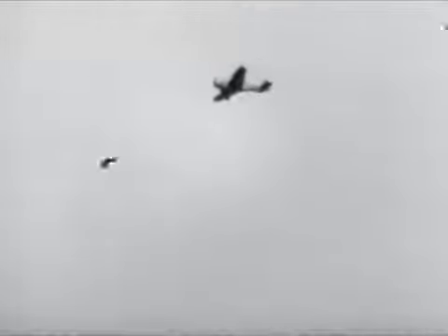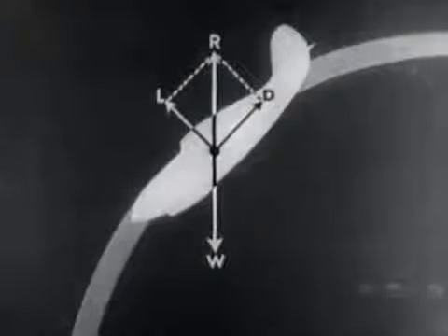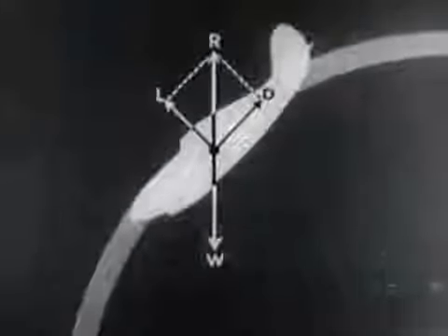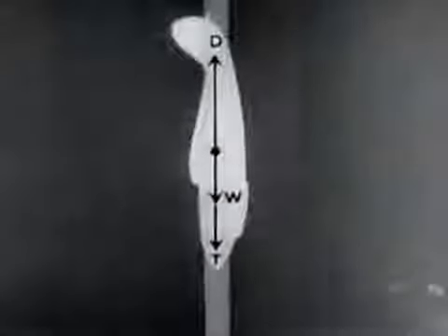Although the angle of attack is constant for any given wind tunnel test, in actual flight, the angle of attack of the airfoil varies with changing attitude and speed of the airplane. Consider the case of an airplane flying horizontally at a small positive angle of attack. As the controls are set to put the airplane into a dive, the angle of attack decreases and the speed increases. Lift decreases, since in this attitude the weight of the airplane is opposed by the resultant of lift and drag. As the flight approaches the vertical, speed increases until the terminal velocity is reached in the so-called vertical dive.